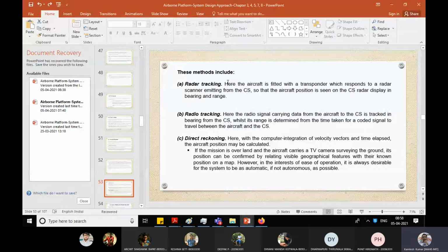So then this is called dead reckoning. This is called direct or dead reckoning. You can tell this is nothing but what is called AHRS, attitude and heading reference system, which is in the INS system. Okay, advanced INS system, because AHRS will give you the redundancy in the sensors, like 3 sensors in each axis. INS system has single sensors in each axis. So accelerometer, gyro, and magnetometer.